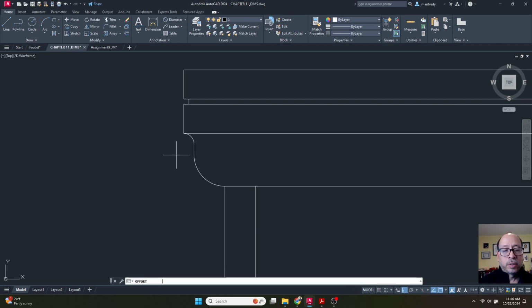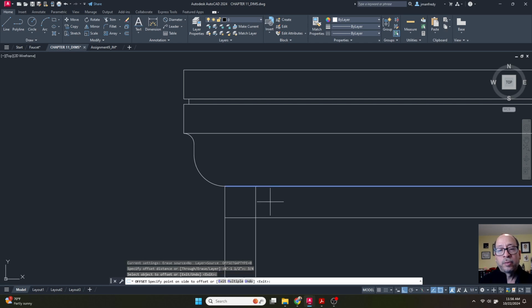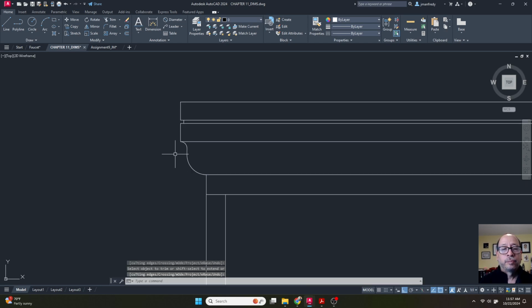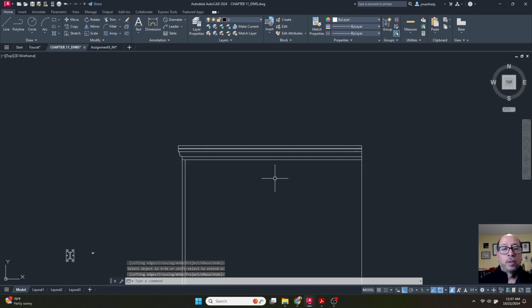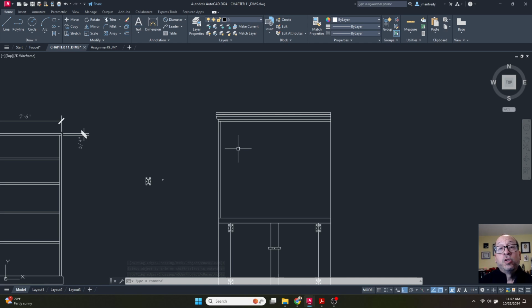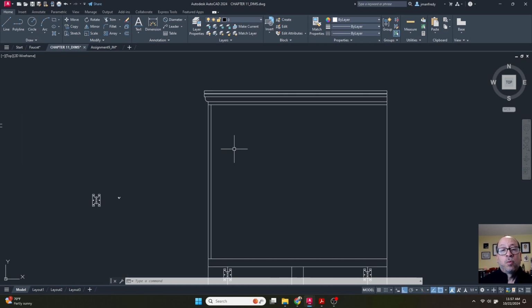They also mentioned that this is a 3/4 inch panel at the top of the cabinet, and it should be continuous through here. So with that being said, we don't want to do that same work twice. There's quite a bit of work going into that. And so what we'll do is when we're done here, we'll copy this to the other side using the mirror command so as not to do the same work twice.